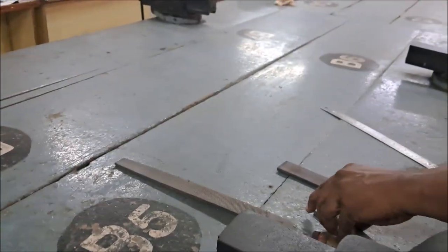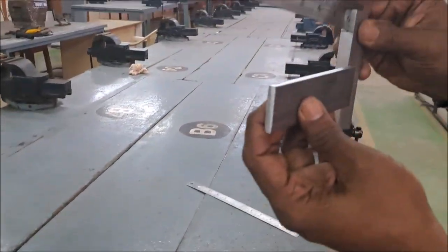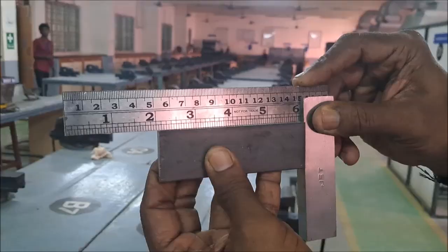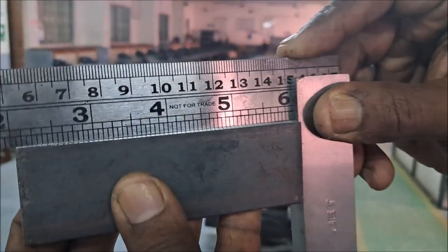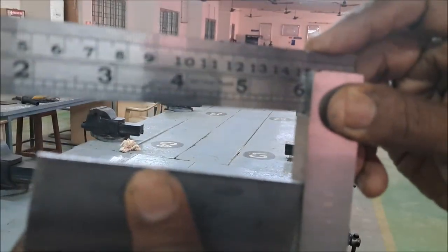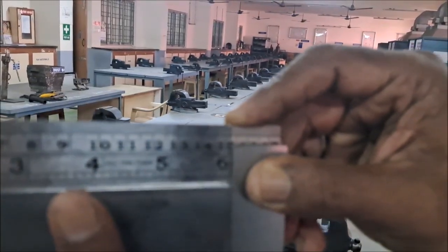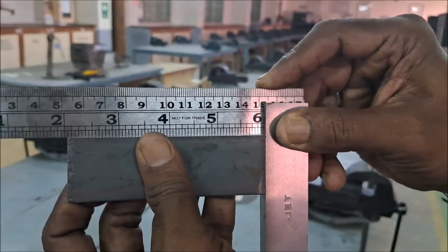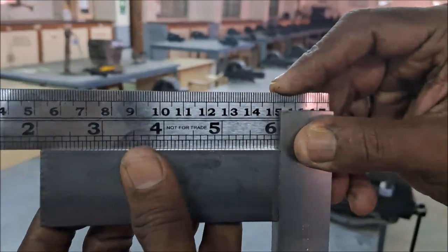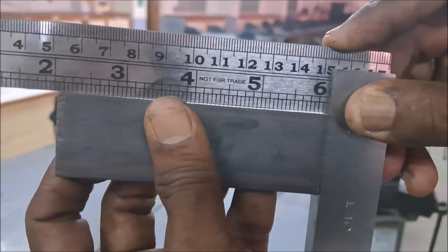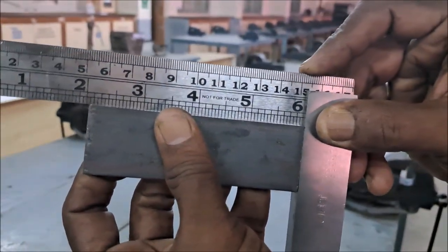After that, check whether your workpiece is 90 degrees or not using the try-square. Like this, you have to support the workpiece on the base and check the 90 degrees. You check it for the two sides, one is the base, another one is the scale side. All the sides you have to check. One supports the workpiece on the base side, and the other automatically gets flat against the scale. Then your workpiece is exactly 90 degrees. Otherwise, if some air gaps are given, it means your workpiece is not exactly 90 degrees. If some gap remains, another portion will be found using the try-square, and you have to file it.